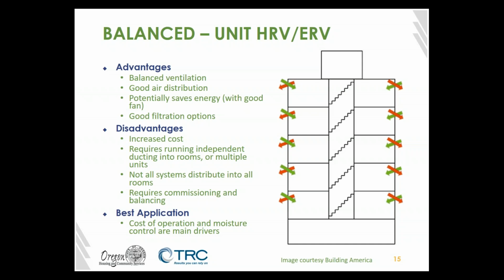That's balanced. And then with an HRV, a heat recovery ventilator, or an ERV, an energy recovery ventilator, you have the added benefit of maintaining some of the cooling that you've accomplished in the summer or some of the heating that you've provided in the winter. And so you're able to salvage some of that waste energy, that energy that would be leaving the apartment, and reuse it with your fresh air, and that has a big energy value, particularly in colder or hotter climates. And the Northwest certainly counts for that. They're very cost effective.